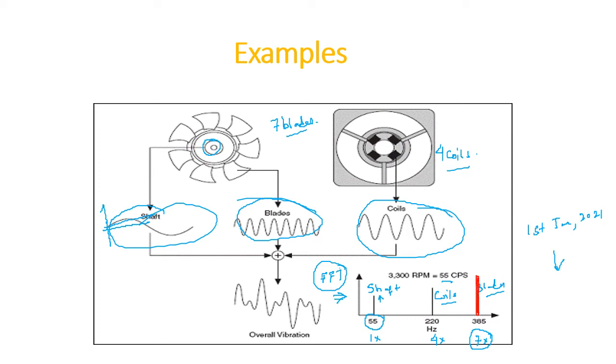Okay, so if you have the earlier data also, now you have data, and you can compare it with the earlier data, or you can simply have some design specification that this is your alarm level. Below this is the safe working. From this to this is your warning level, and after that it is danger. So you can make the report and hand it over to the maintenance group.